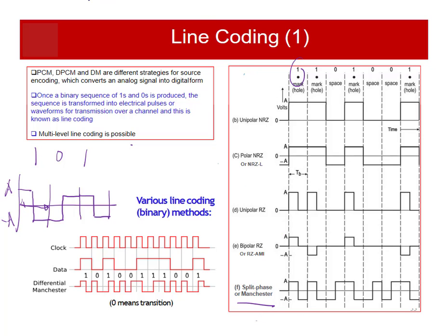If you take another course in future, 445 digital modulation, you will get better insight about line coding. But for now, unipolar NRZ and polar NRZ will be enough. I was just giving some more insight, but you will mostly need these two. For unipolar, 1 is high and 0 is null. For polar NRZ, you have high for 1 and low, the negative of the high, for 0. Let's say if it is 5 volt, then you will have minus 5 volt for 0. That's all you need to know for this course.